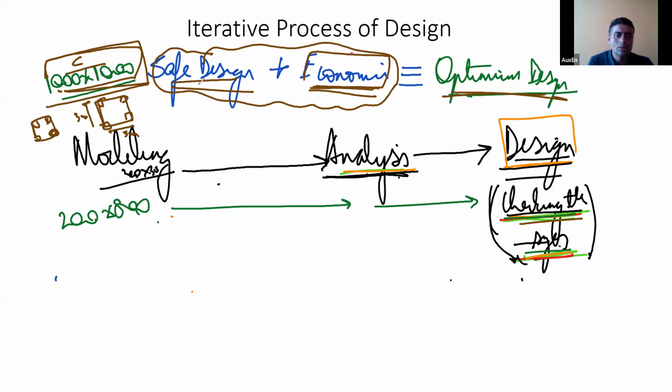All right. So let's not only focus on one aspect, but focus on both the aspects. That should be the job of a structural engineer, to work out optimum solutions. So what I was trying to tell you, that I suppose I provide a 200 by 800 mm size. It's a small span, not very heavily loaded. And while checking the size, when I find out the reinforcement, etc., I can quite clearly see that this size is safe, but it's over safe, as we usually say.